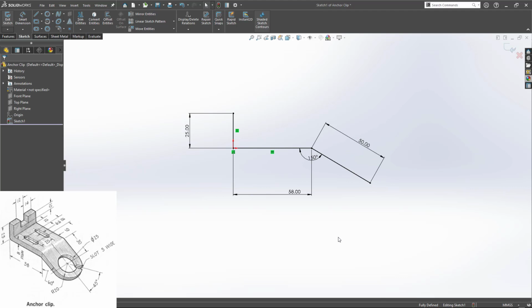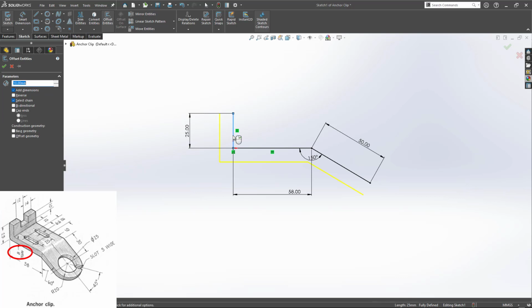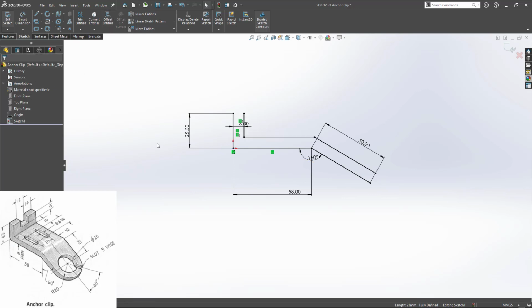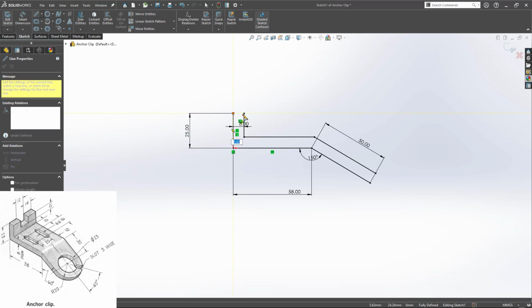Yep, this is done. The thickness they have assigned is 8. Second is the offset. Chain is active. Select everything, just mention 8 and reverse it. Looks perfect. Yeah, I can close it by using the line tool. These two done. They have assigned the radius.